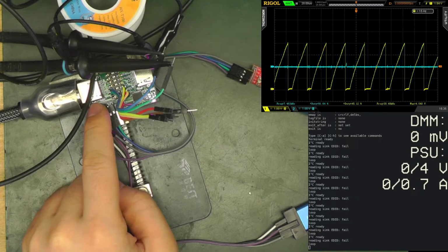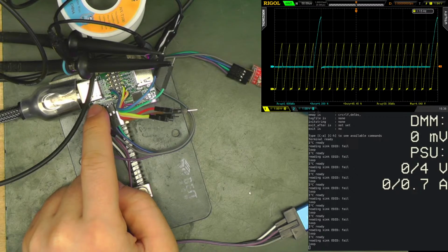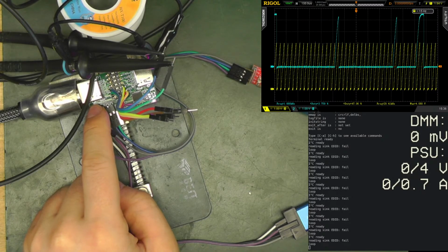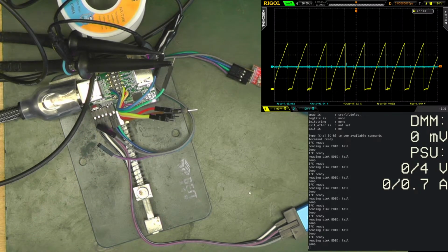The yellow one is the clock and the blue one is the data. We see there is some data, but it is too fast. So I can decrease the speed, and we will decrease the speed, but I'm wondering why it is so. It looks crap. So the pull-up resistor is not strong. Let me check. I thought in the specification I saw the pull-up resistor should be stronger.